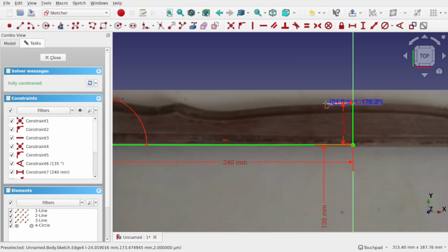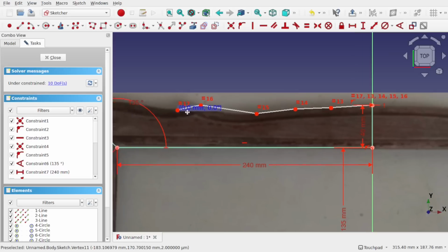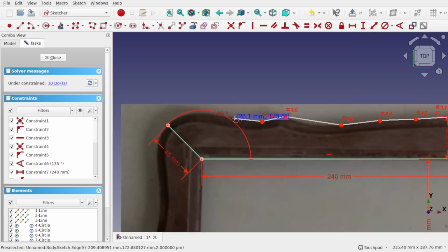And what I'm going to do is just move along, and I'm looking for changes. So I can't do that as a straight. I have to drop the points of the B-spline at the points of change. So I'm going to move this one up a bit actually. So we come up to here and come down. You may want to add more, may want to add less. This can be a bit trial and error to get this right.